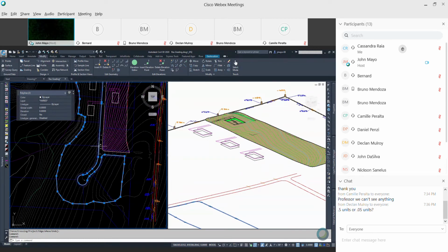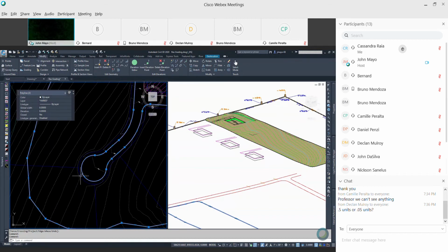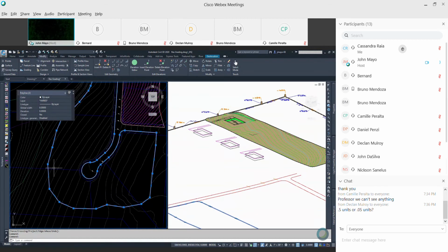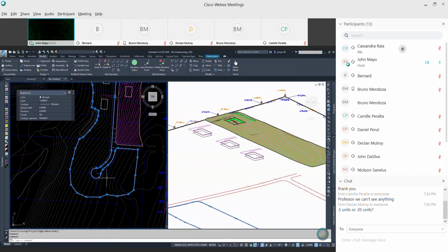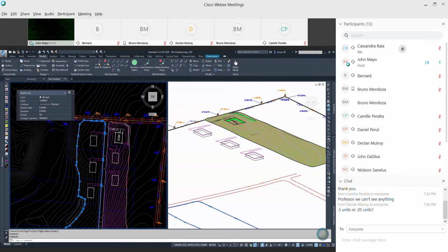That's because the proposed surface is going to create a U around that road. You want to avoid it. Divide your surface into two pieces, or you're going to use a boundary, a border on your surface to prevent the triangulation between there. But I'll leave it as one for now so you see the issue.